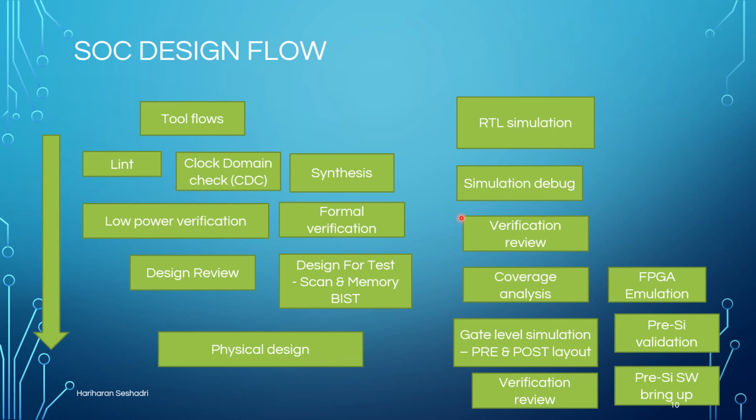Verification is happening in parallel. That's why I showed you here in parallel. RTL simulation. It takes the RTL and the test bench we spoke about in the previous slide. You run simulations. A lot of automation is needed there. That's why, again, Perl, assertions, there are advanced topics. That's a separate course by itself. This is only an overview, right? You run simulation, debugging simulation, extremely important. Believe me, this is a challenge, the most challenging job. If you can do this, you get a job in industry.